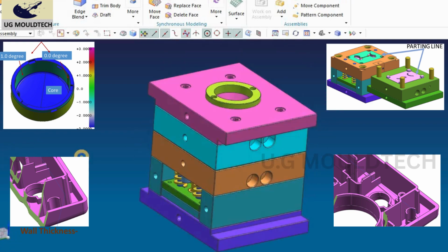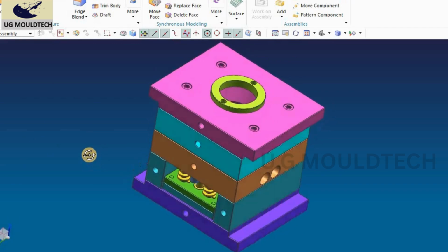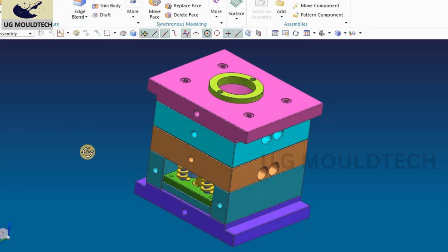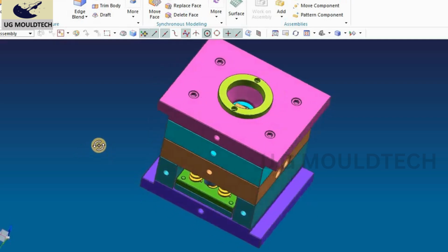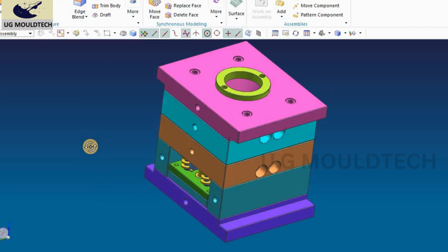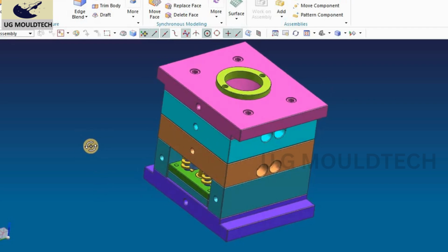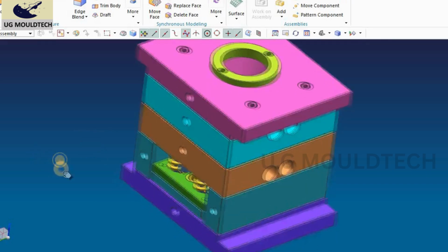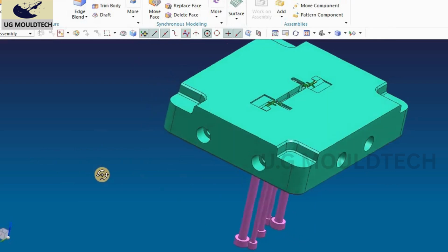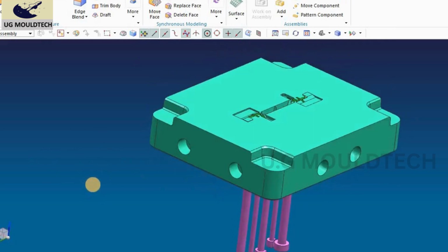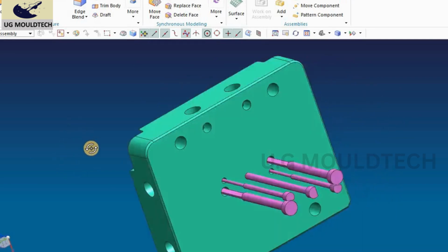tool. Okay, friends, the next part will be extracting the design data before creating the 2D drawing. We extract important design data from the CAD, like overall dimension, feature size, holes, and specific material. Some CAD software also generates an automatic report of the volume and weight, which is useful for our mold calculation. Friends, you must check thoroughly the parting line, core, and cavity inserts before going to the 2D drawing. This defines how the mold opens and ensures proper ejection of the part.